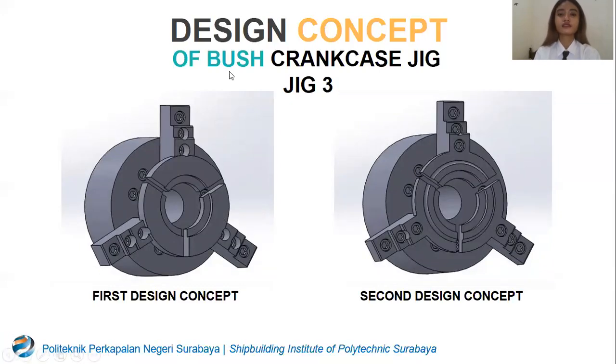And last, this is the design concept of the bus crankcase jig for the third jig. This is the first design concept, and this is the second design concept. For the first design concept, this jig has a simple design, is strong, has an affordable material price, material that is easy to get, easy jig operation, and is easy to manufacture and easy to repair.